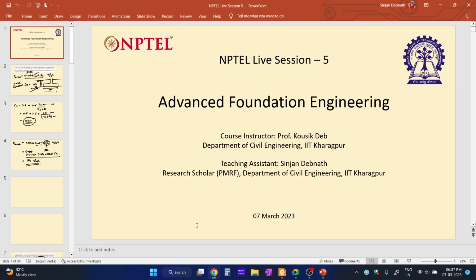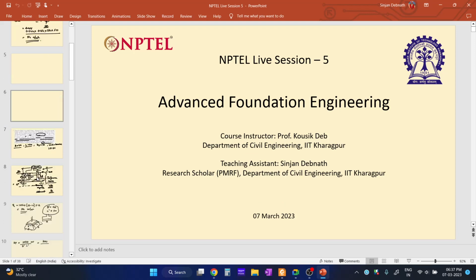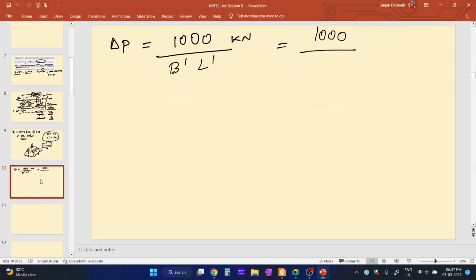So I hope you are able to see my slides. So 1000 divided by how much it was? It was 4 into 5. So if you calculate this, the additional stress that the 1000 kilonewton was causing at point A will be 50 kilonewton per meter square. Okay, so now we need to find out the consolidation settlement.